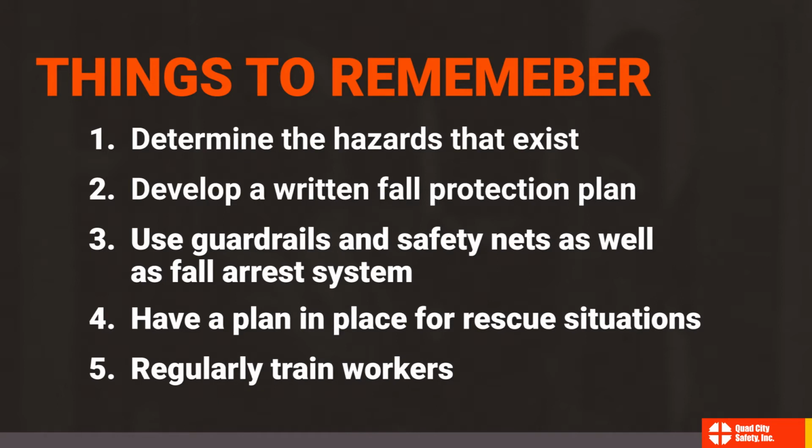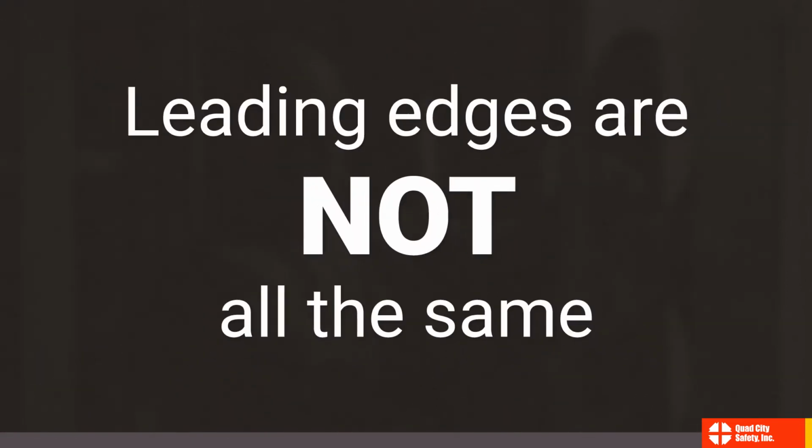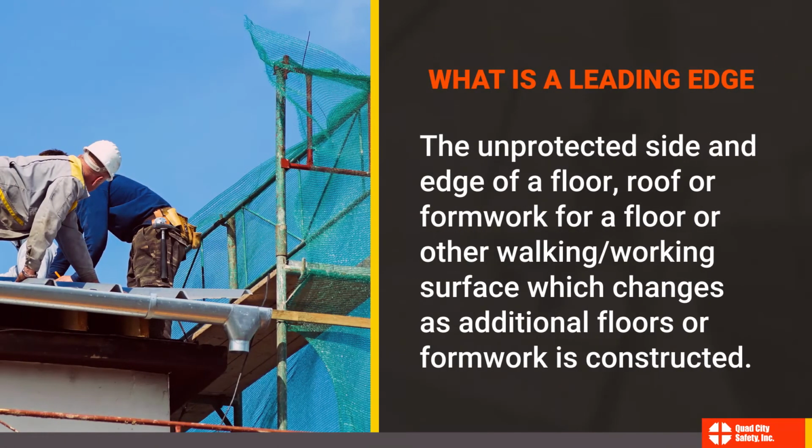So you've planned for most risk factors on the site. When do you need self-retracting lifelines with leading edge? All leading edges are not the same, so let's explain a few terms. What is a leading edge? Well, a leading edge means the unprotected side and edge of a floor, roof, or formwork for a floor or other walking, working surface which changes as additional floors or formwork is constructed.